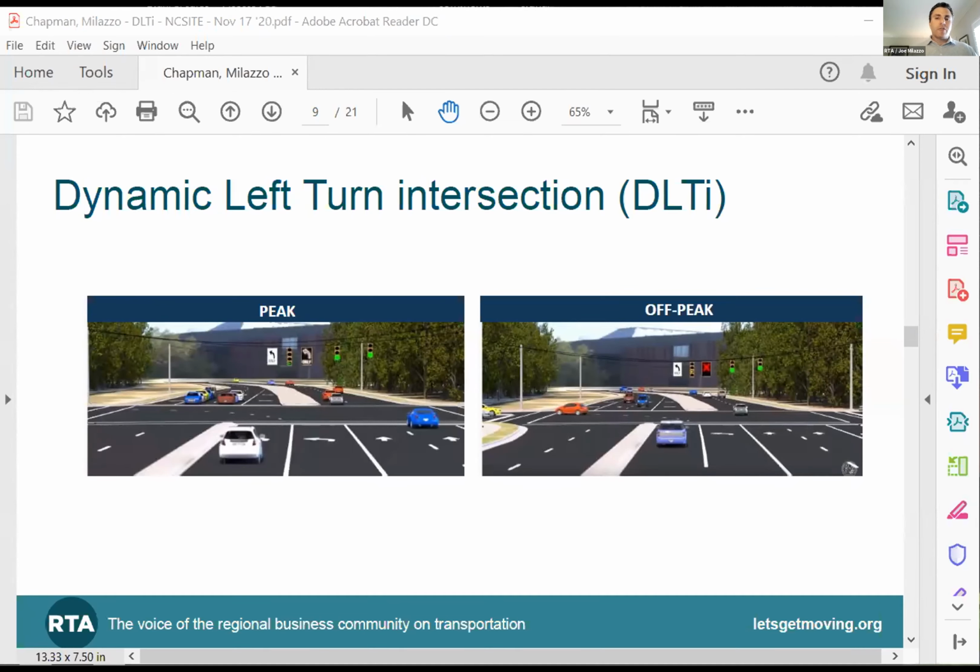Another thing you wanted here is sight distance. Again, sufficient sight distance for left turning drivers, for permissive left turns from either lane, since it was the first one around. As this continues to evolve, the best locations for this are going to be places where the rightmost lane is more marginal. If both left turn lanes have good sight distance and there's no real issue of swept path under permitted phase, then your dual left flashing yellow arrow is a superior design over this,